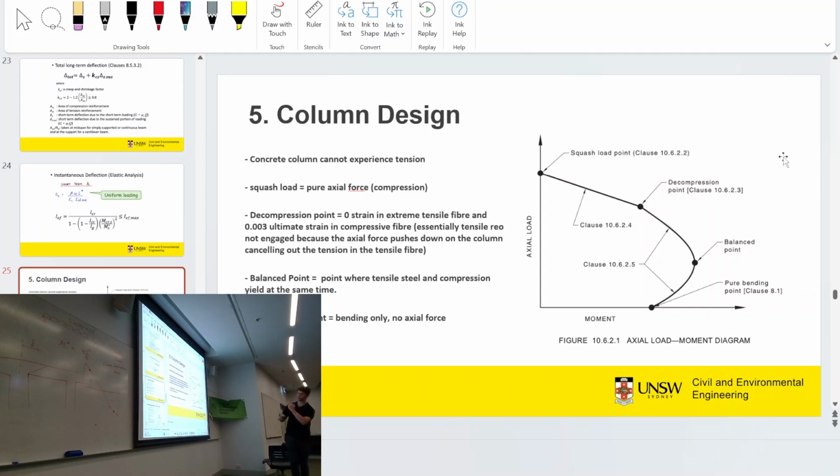If I bend the column, it'll break at a certain amount. But if I take that same column and apply compressive force, it's going to get stronger. Why? This is just a guess. Is it because you put slightly more of the concrete into compression, where it becomes stronger? Very nice, that's exactly right. So you have this column that's bending, like a beam rotated 90 degrees. One side of the concrete is in compression, one is in tension.